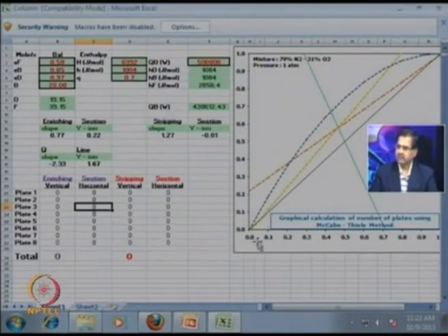The operating line for the stripping section also has an intersection at y equal to x, which is at 0.05, because it depends on the impurity of the bottom product, the amount of nitrogen it has, which is 0.05. So, this is my first point here, and its y-intercept is minus 0.01, which could be at this point. If I join these 2 points, I will get the operating line for the stripping section. So, this is my operating line for the stripping section, and this is my operating line for the enriching section. I have plotted these lines.